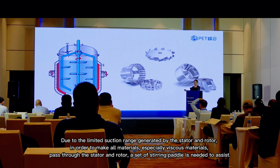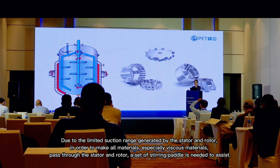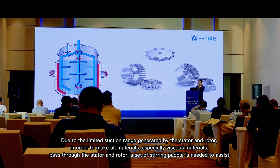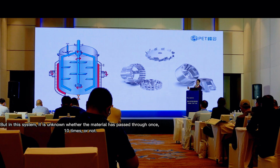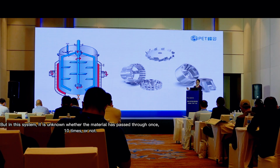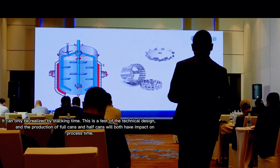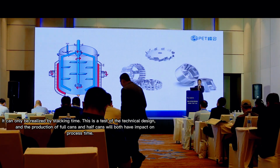Due to the limited suction range generated by the stator and rotor, in order to make all materials, especially viscous materials, pass through the stator and rotor, a set of stirring paddles is needed to assist. But in this system, it is unknown whether the material has passed through once, 10 times, or not. It can only be realized by stacking time. This is a test of the technical design, and the production of full cans and half cans will both have an impact on process time.